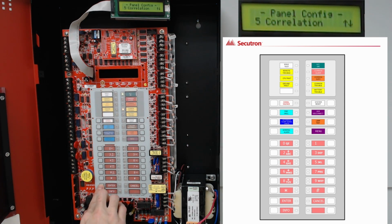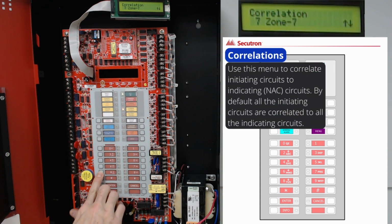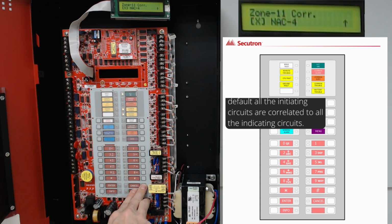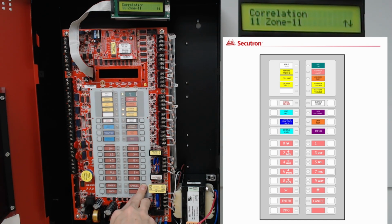The next option under panel config is correlations. By pressing enter, we'll enter into the correlation options. We'll see our zones 1 through 12. With any one of our zones, we can hit the enter button to select it, and then select what NAC circuits will operate when that zone activates. We can hit the left or right cursor arrows to unapply the X, so the NAC circuit will not turn on when the zone operates, or again, hit it to reapply. Once we're done with our selections, we can hit cancel to exit back out to the previous menu option, and then cancel a second time to go back out to our panel config options.